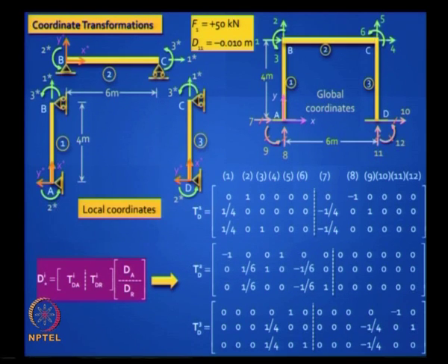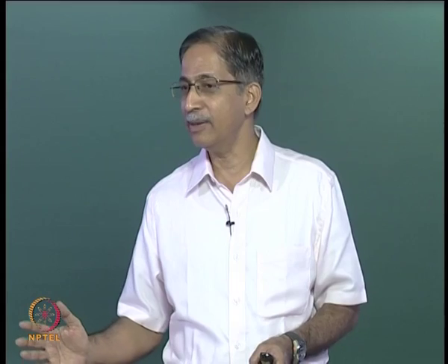You have got assignment problems where you really need to sit and solve. So my suggestion is go through it carefully and do it. There is one more suggestion I can give you. If you want to minimize your work manually, you can throw away half that matrix, you can throw away all the restraint coordinates, because you can get those reactions from the member end forces anyway, right.